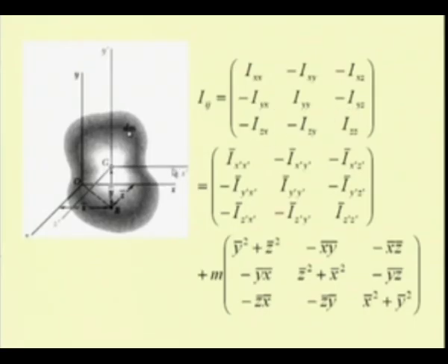So, now we have, when we write all these individual quantities in terms of their centroidal axis, and the location of the centroid, that is x bar, y bar, z bar in this coordinate frame O, x, y, z, we have this as the inertia tensor in the centroidal frame of reference plus m times y bar square plus z bar square, minus x bar y bar, minus x bar z bar, etc. We already know that these are the coordinates that we have obtained from the parallel axis theorem.